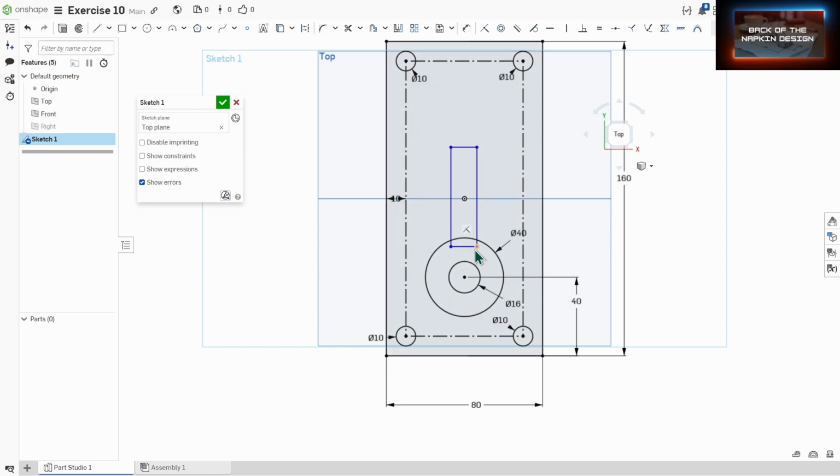And let's do some dimensions from the left side to here. We found that this is 35. And the left side to here is 45. We're going to push this all the way to 115 plus 25, which is the radius size. So D for dimension, click in here. So we got 115 plus 25 and that sends us to that location.